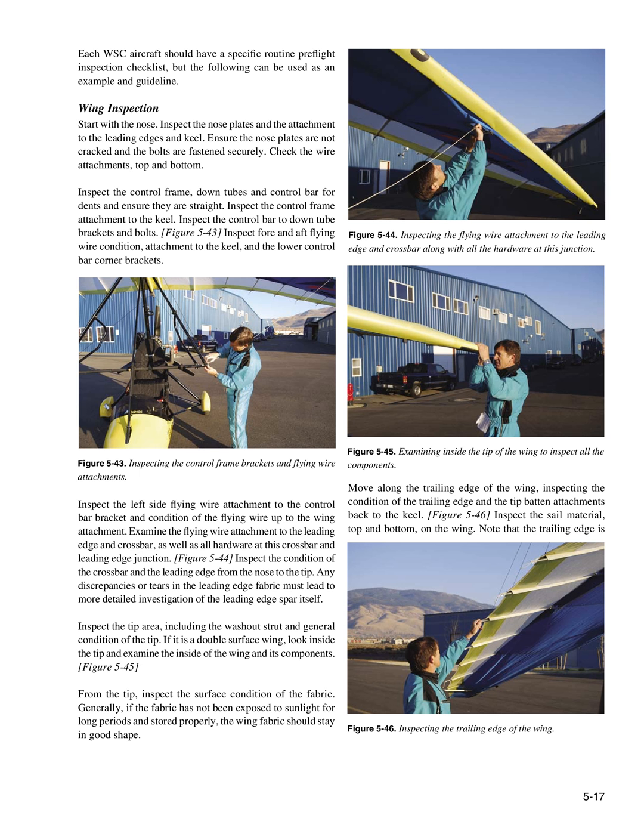Inspect the control frame, down tubes and control bar for dents and ensure they are straight. Inspect the control frame attachment to the keel. Inspect the control bar to down tube brackets and bolts. Figure 543, inspect fore and aft flying wire condition, attachment to the keel, and the lower control bar corner